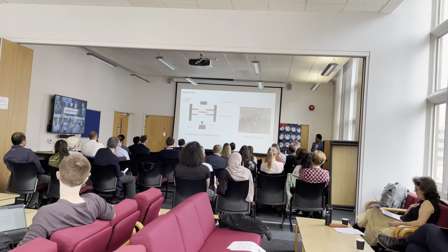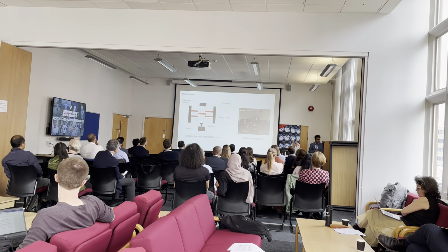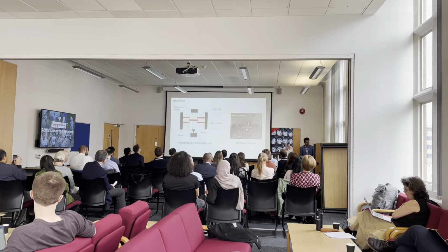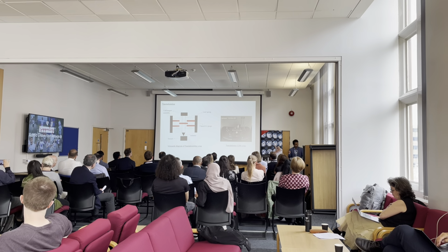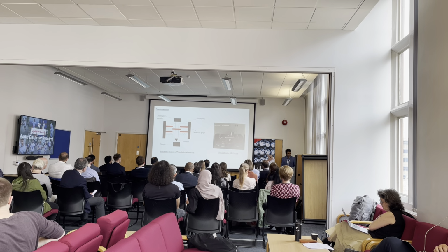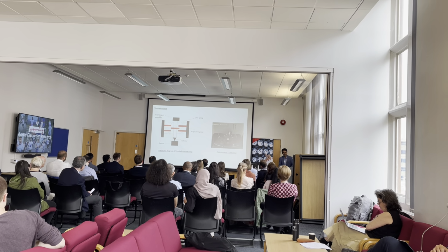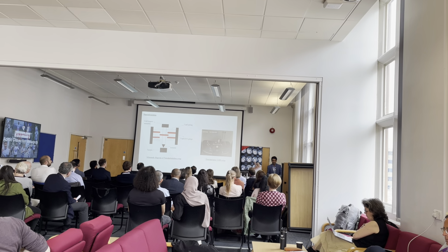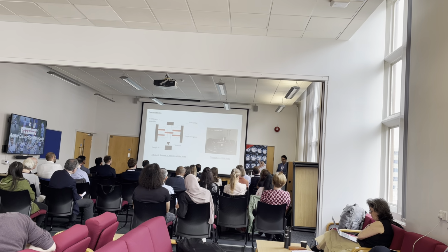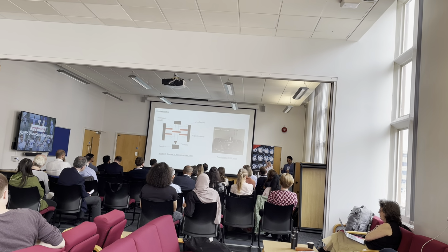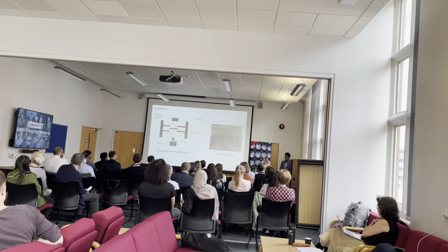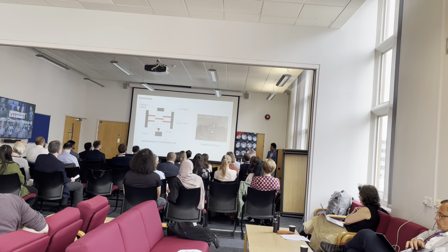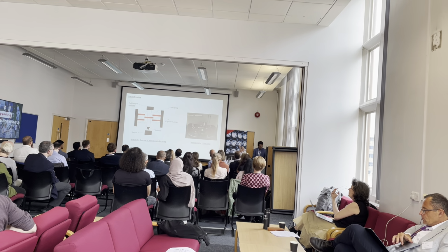The other set of experiments was using a nano indentation setup in which we had a coil magnet assembly. You can see the schematic of the G200 setup, which was utilized here. On the left hand side, you can see the coil magnet assembly, leaf spring, capacitive gauges, and the indenter. Essentially, we were trying to increase the frequency of the indentation up to 10 Hz. The reason we went to 10 Hz is that we were also trying to understand if at this frequency we could see a fair comparison between the micro length scale and the macro length scale, because at the macro length scale, we went up to a frequency of 5 Hz. On the right hand side, you can see the G200 setup here.